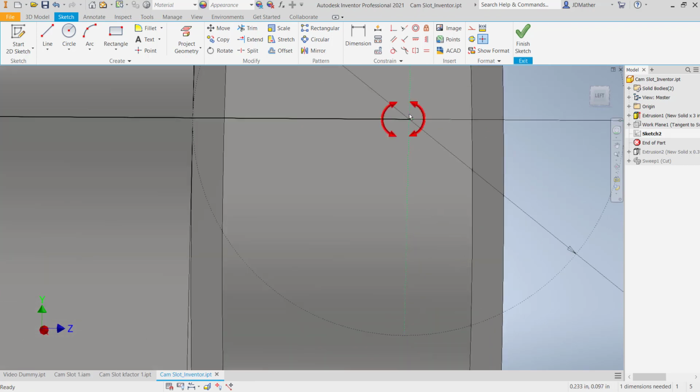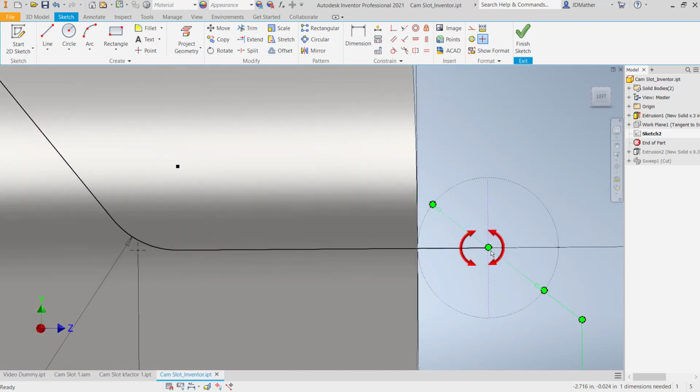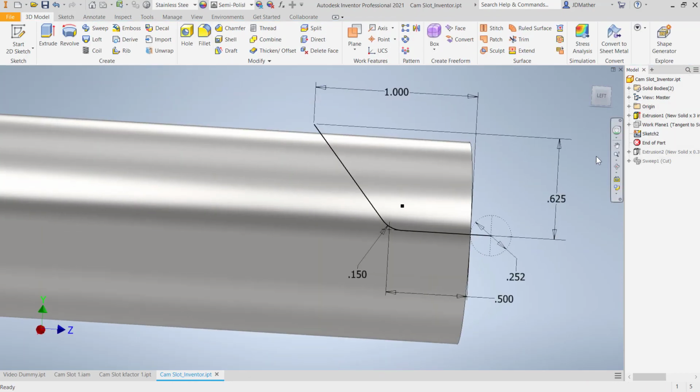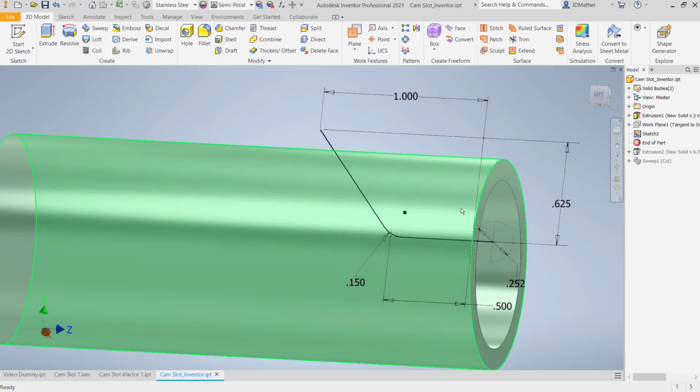Okay, so I have a point in here that still has a rotation. I was doing something earlier. Oh, there it is. This line right here, that line can still rotate. And so these arrows, when I just turned that on, showed me where that rotation was at. And I'll put a constraint on that line, and now it's fully defined. It tells me down here it's fully constrained. The degree of freedom arrows turned off, and then I wrap that around this curve.